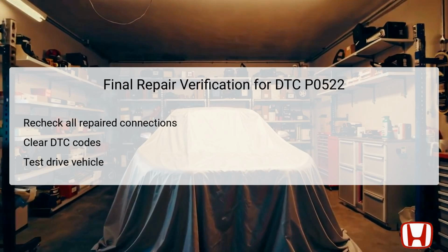In the final repair verification stage for DTC P0522, it is imperative to double-check all repaired connections to ensure reliability. After reconfirming that all electrical connectors are secure and clean, clear the DTC codes from the system using the HDS. Following this, perform a test drive to monitor the vehicle's performance and ensure the check engine light does not reactivate.